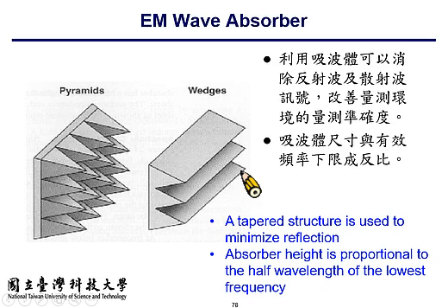Because at the very bottom of the absorber is what? Is the metal plate of your anechoic chamber. So let's describe it in terms of resistivity. The resistivity of the metal plate is 0. But at the front, you have 377 ohms for your free space propagating wave. So you need to provide a transition from 377 to 0.